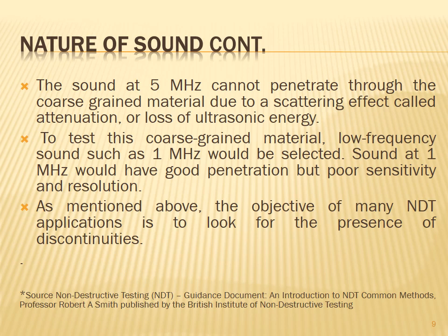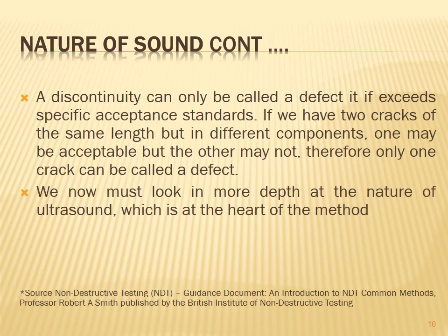As mentioned above, the objective of many NDT applications is to look for the presence of discontinuity. A discontinuity can be many different conditions. Cracks, slags, porosity and stringers are the names of just a few. It would be wrong to use ultrasonic inspection to locate, for example, a crack and then to refer to the crack as a defect. A discontinuity can only be called a defect if it exceeds specific acceptance standards.